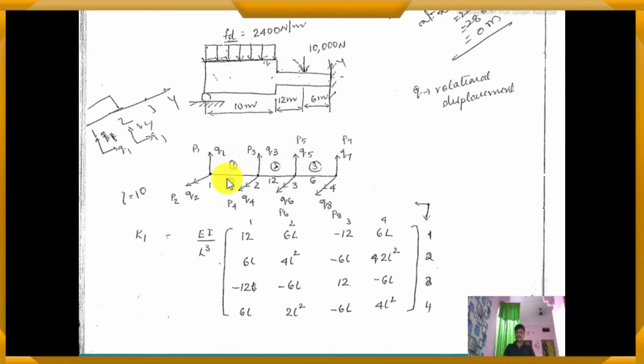Now this is the discretizing of the body diagram into a line diagram, the finite element discretizing method they have made. In a beam element at each node, as you know, there will be two deformations: one is vertical deformation, another is rotational deformation. This will be node 1, here node 2, node 3, node 4. So there are 4 nodes and 3 elements. This will be element 1, element 2 and this will be element 3. I think it is clear to you.